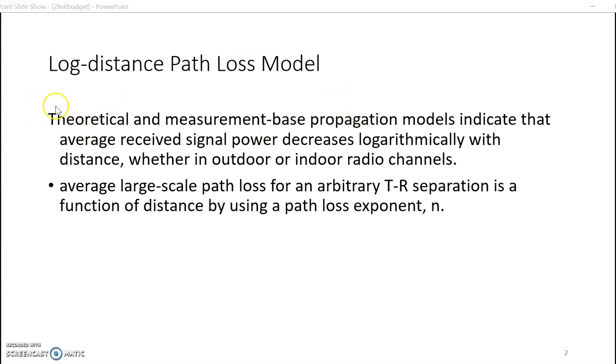Theoretical means you will have some mathematical expressions, you will substitute some values, and then you will get the received signal strength. Measurement based models means at different environments, at different distances, you can transmit some signal and you can measure the signal by using some power meters. So both these models say that the received signal at the receiver decreases logarithmically with distance.